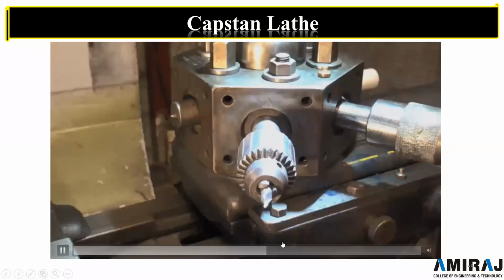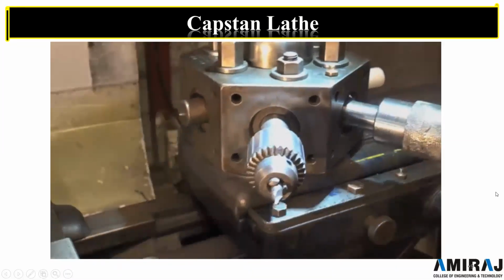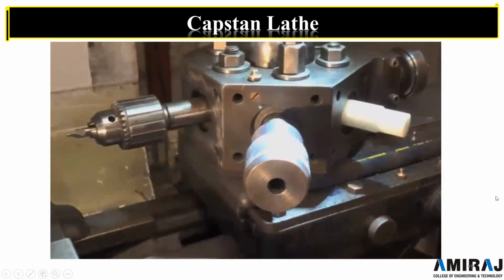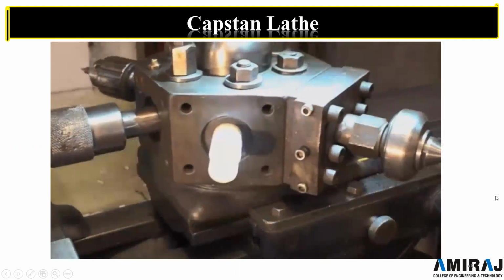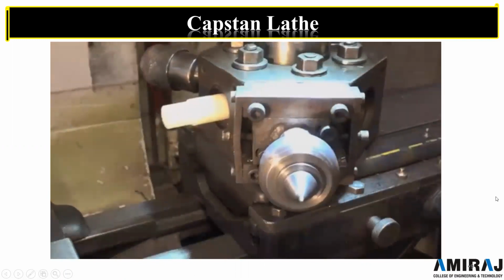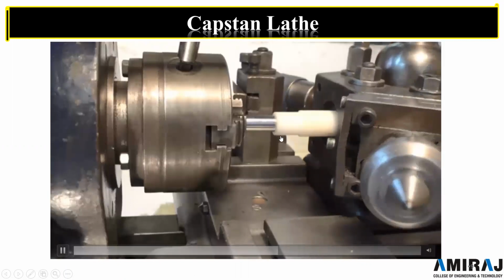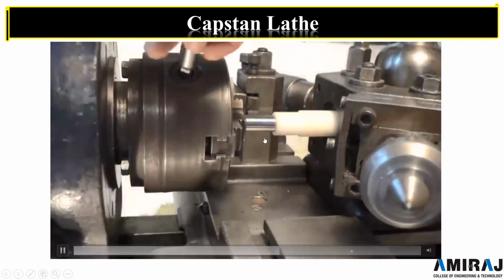I maintain a centre drill, a keyless chuck, a bar stop and a live centre. Having various accessories loaded in the Capstan saves considerable time over having to change items in a tailstock for each process. The bar stop is used to set the position of the material in the chuck when making multiples of the same part.